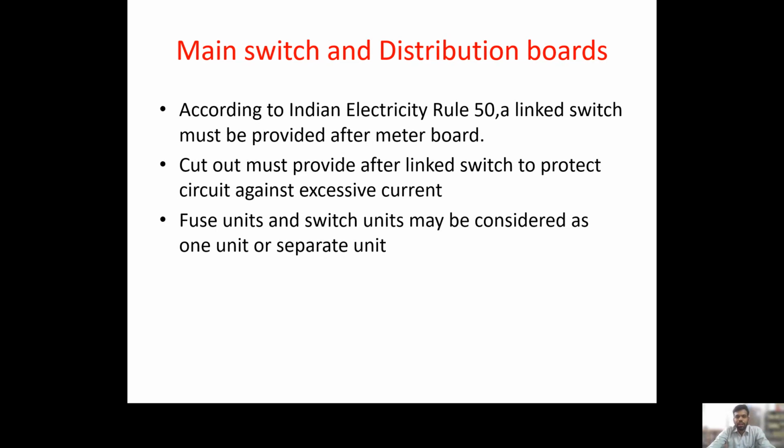Here, according to the Indian Electricity Rule 50, a linked switch must be provided after a meter board. In the previous module we studied the different Indian rules. In that, rule number 50 says that a switch must be provided after the meter board.